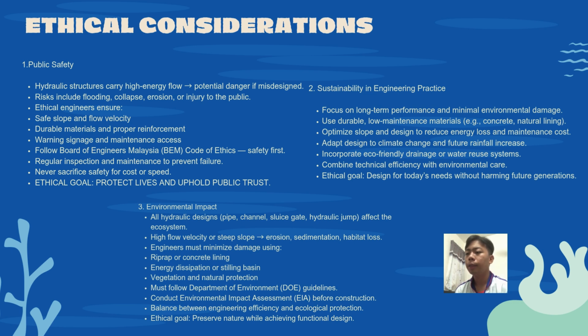Engineers must minimize damage, like using riprap or concrete lining, energy dissipation or stilling basins, vegetation and natural protection, and also must follow the Department of Environment DOE guidelines, conduct an environmental impact assessment EIA before construction, and balance between engineering efficiency and ecological protection.